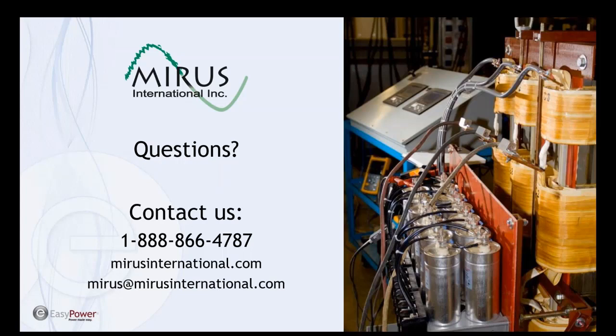If we do see 3rd harmonic, it's zero sequence, so it's not going to be affected by capacitors that are connected phase to phase. So we design below the 5th so that when we connect to the power system, which is inductive, the inductance of the power system is going to lower that resonance frequency further. If it starts at 4.7, it's going to take it down even lower if you have inductance in the power system. If you're going lower, you're moving away from the harmonics that are present.